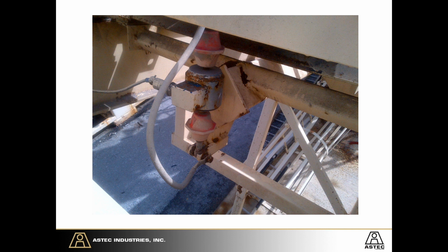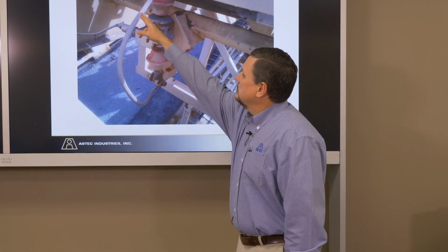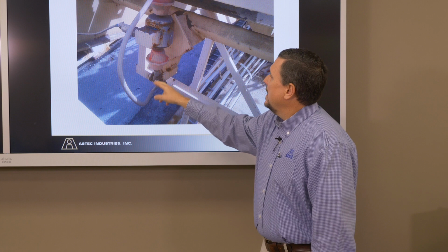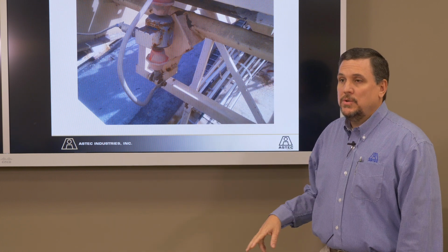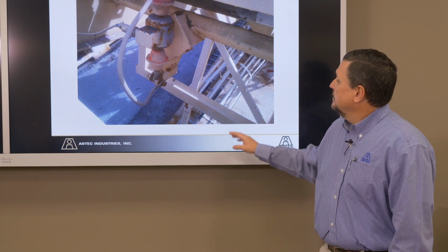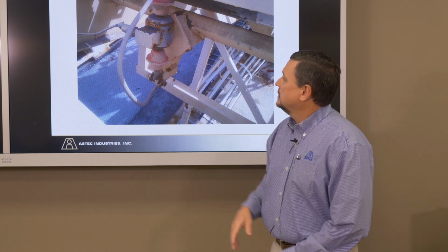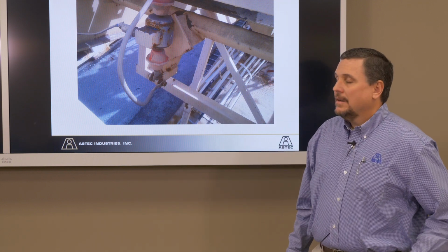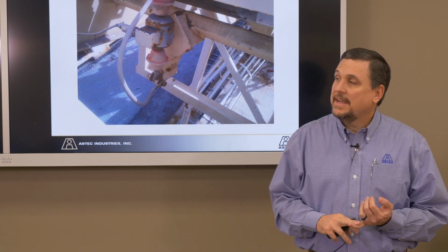You'll see a few other things too here. There's some insulators, that's these red items. And then you'll also see a cable that goes around that. It's for two things. One's for lightning protection, and two, if there's any type of welding or anything done on that conveyor, it can actually direct that around the load cell and will not burn it up. Lots of times on the lightning strikes, the load cells and the tacks are what take the hit.